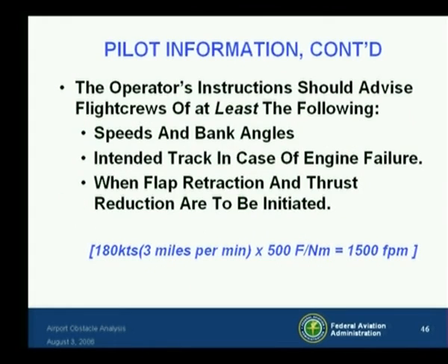Now, continue here, the operator's instruction should advise flight crews of the following. This may be accomplished as a general policy for all airports, with exceptions stated as applicable or specified for each airport. But at least you ought to be covering speeds, especially relative to V2 and bank angles to be flown, both in all engines operating and one engine inoperative considerations.